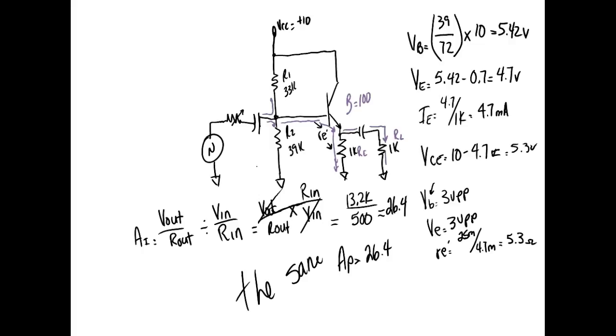Is it going to cut off or is it going to cut on? No base current, guys. What's it going to do? It's going to cut off. So what should we measure across here? It's an open element in a series circuit. What should the voltage collector emitter go to? 10 volts. Okay, so that's what we anticipate, right?